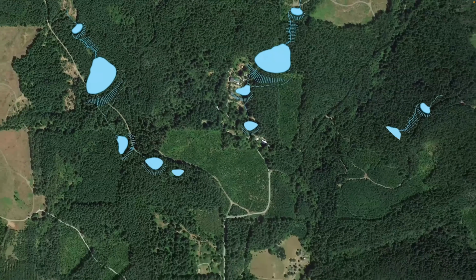Another element to consider in the process of construction of the spillway is the trickle tube. A trickle tube is classically used to minimize small seasonal flow over the spillway. So this cuts down on just the long-term erosion of a small trickle as it moves over the spillway.